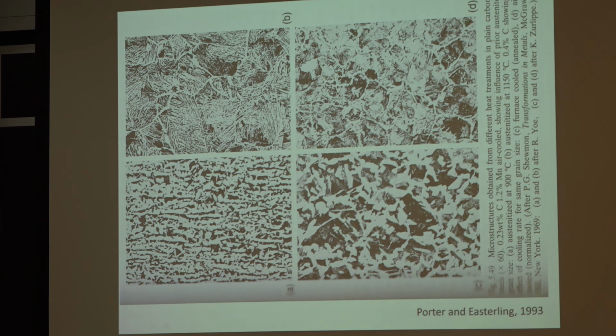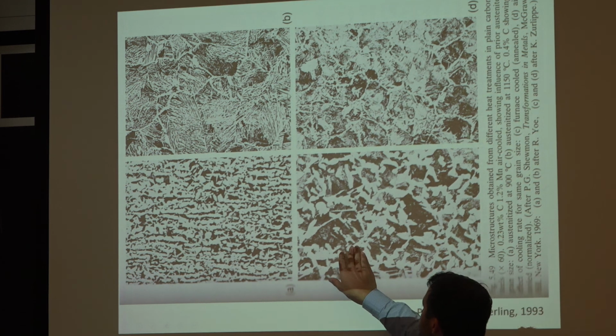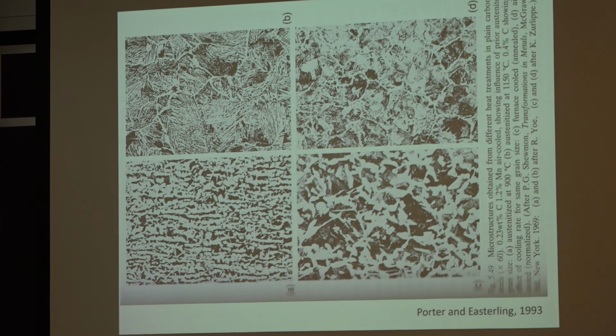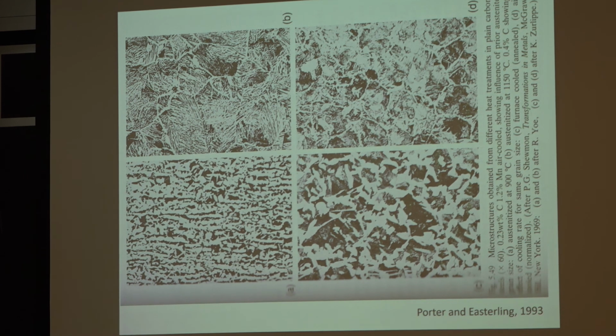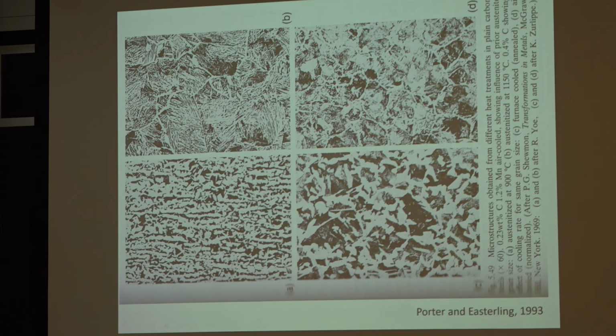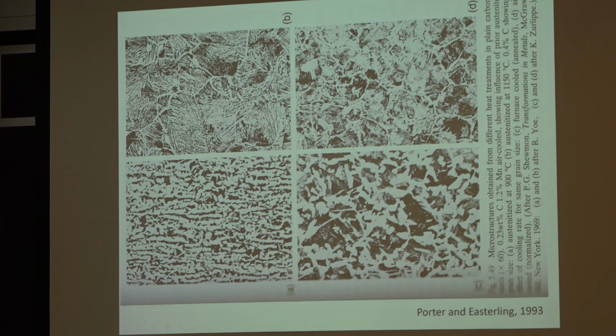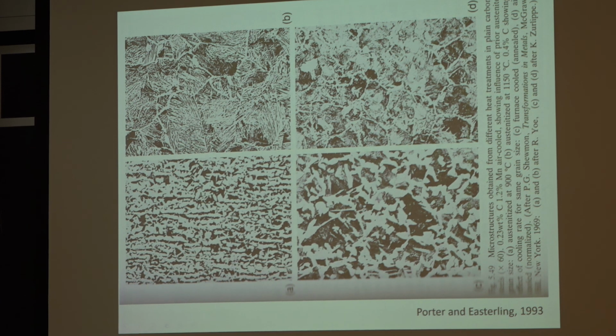They just look very different, right? In this case, this is the low strength case where you got big grains of pure iron that are going to drive your yield strength. So it's going to be very, very low strength. And then the other case here is it's all intermingled, and that's your high yield strength, low ductility and toughness. And there's a bunch of combinations you can do. Generally, if you're going to quench steel, almost all the time, you reheat it up, and that's called tempering. So it's a very, very different process.